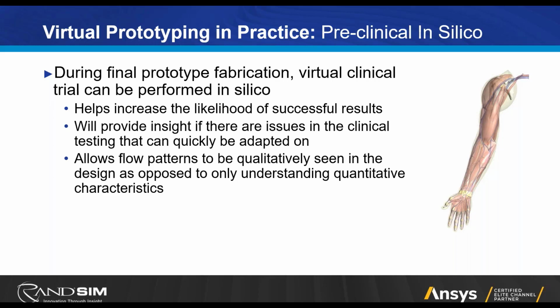And one of the great things with CFD that I'll touch on a little bit later is you don't have to rely on a lot of the limitations you have for material properties like you might in a lab. So in a lab, you're often using something like glycerol or some artificial blood to really model out the flow profile within a pump. Whereas in CFD, we can use pre-built models for non-Newtonian flow behavior, for hemolysis, thrombosis, whatever these might be, to actually really evaluate how we see things happening in reality or how we would expect to, especially when we have that validated model against some of our benchtop experiments. We know that it's going to correlate better with reality.